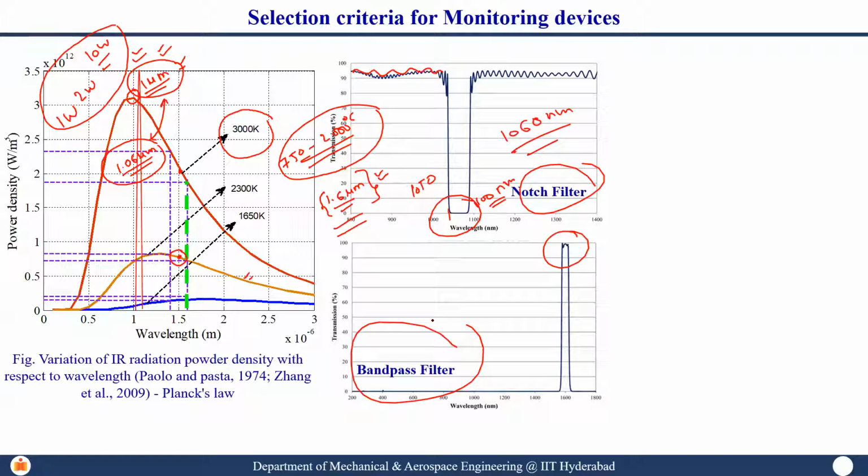Now we assume, fine, you got notch filter, you got band pass filter, you got the detector, and you targeted working on aluminum, and all of a sudden you got a project and you started working on steels or nickel based superalloy. Now previously the pyrometer measuring range is, let us say, 0 degrees centigrade to 1000 degrees centigrade.